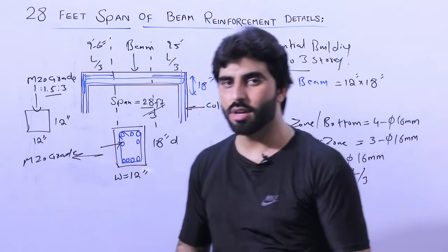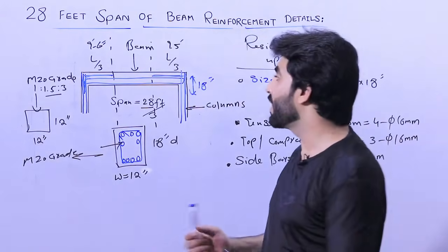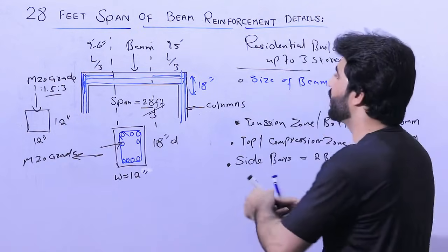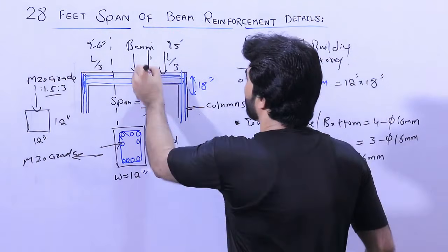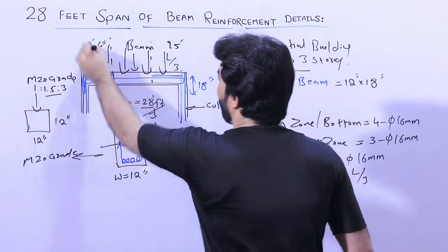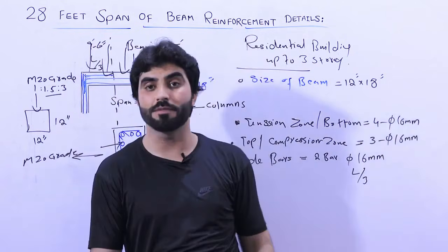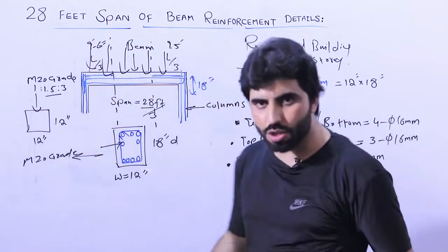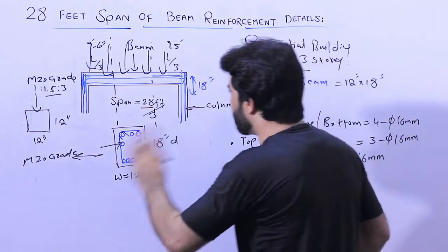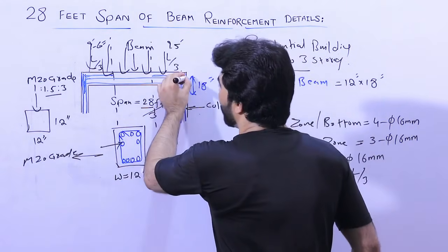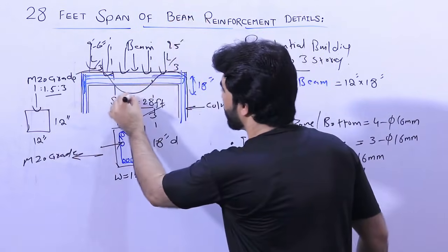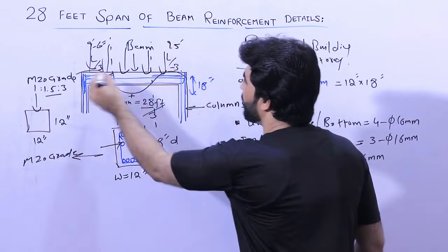So therefore the extra steel rod should be provided at the distance of L/4, because we have negative bending moment. How? Like this. When the load comes on the top of the beam like this, already we are providing the beam, because on the top of the beam we have the structure load, brick masonry or any other structure we can provide on the top of this. So when the load comes on the top of this, it makes a shape same like this. Look at here. So here we have positive bending moment. Here we have negative bending moment.